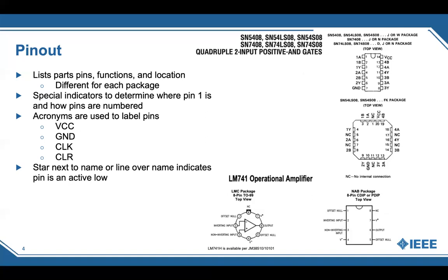And another thing about pinouts to note is that a star next to the name or a line over a specific name typically indicates that a pin is in an active low state.